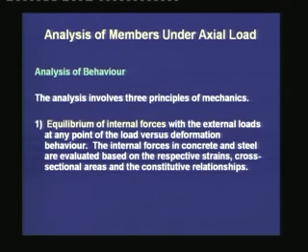The internal forces in concrete and steel are evaluated based on the respective strains, cross-sectional areas, and the constitutive relationships. Here we are learning some other new terms, that first of all, the forces are related with the strains in the individual members. It's also related with their cross-sectional areas, and also it is related with their constitutive relationships. Constitutive relationships are the relationships between the stress and strain for individual members.